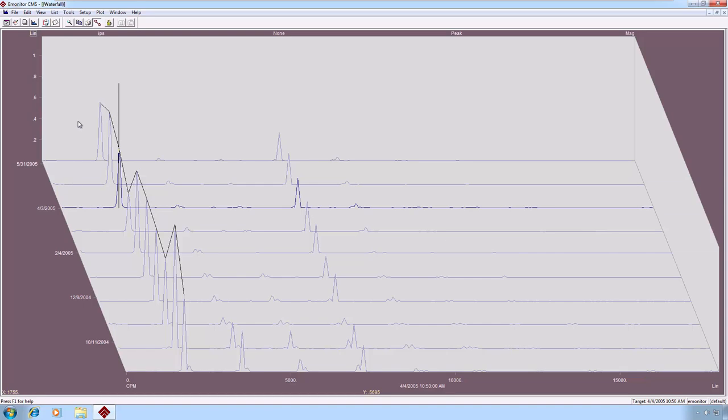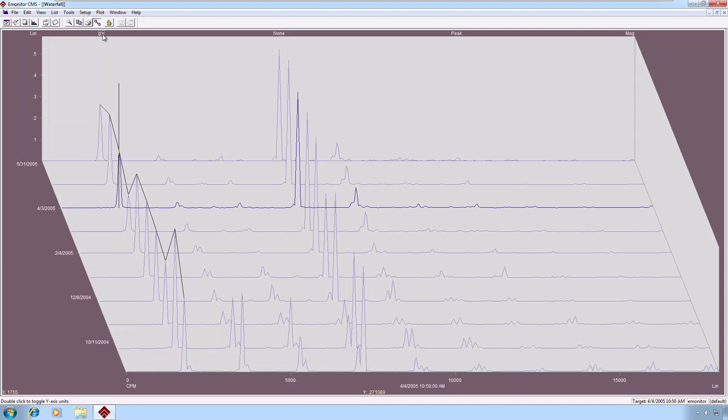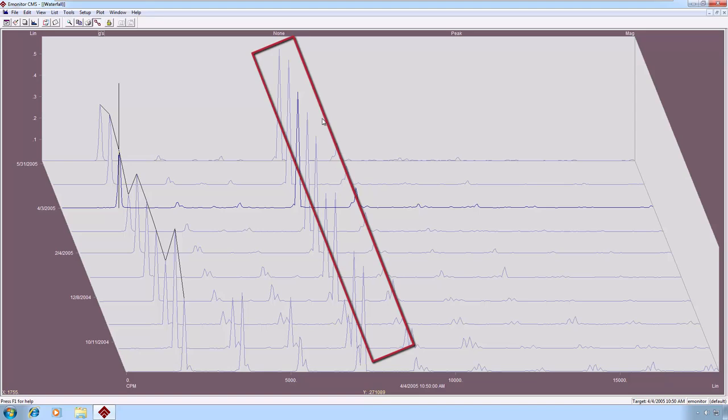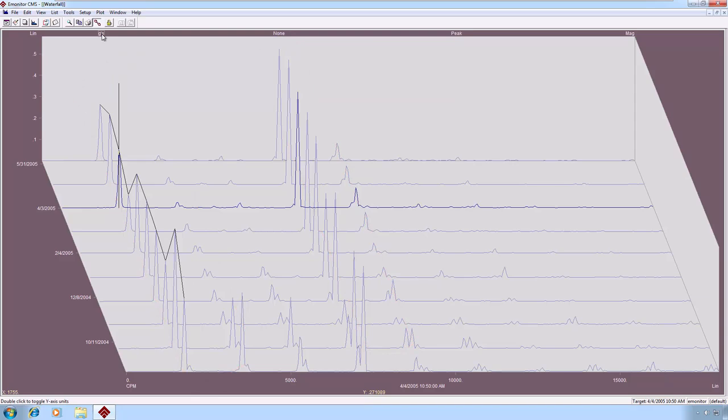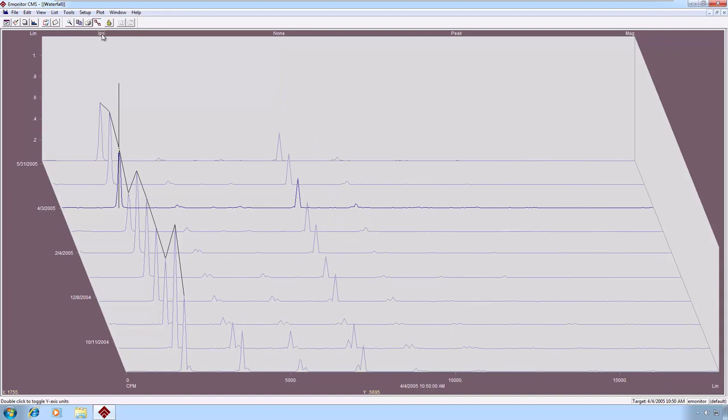Some other interesting things about this plot, as with a standard spectrum plot: the inches per second units can be toggled to scroll through different units, and the amplitude scale will rescale to reflect those units. You can also choose Gs, for example, which accentuates higher frequencies and suppresses lower frequencies, often the units you will use for watching bearing defects. If the default units you're taking data in are inches per second, and you'd like to see what it would look like in Gs, you can interpolate this on the fly. We'll put it back to inches per second.